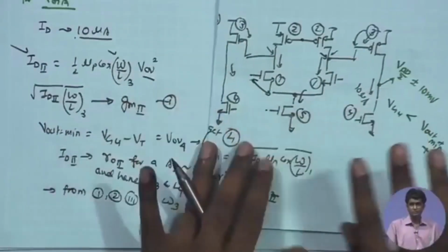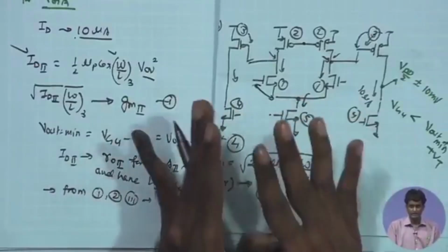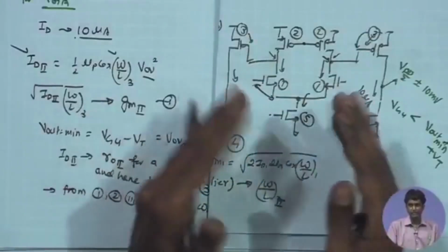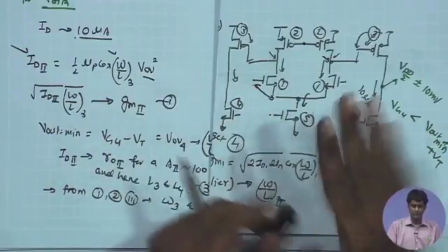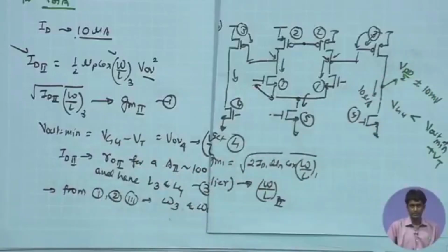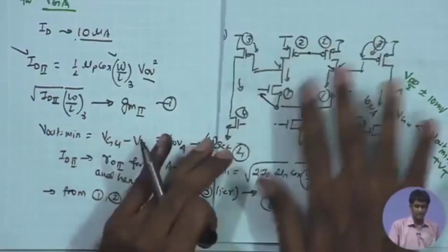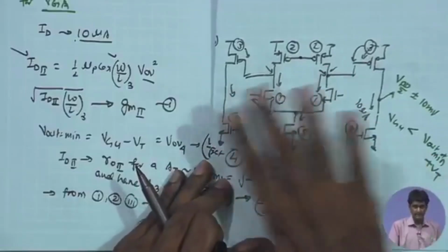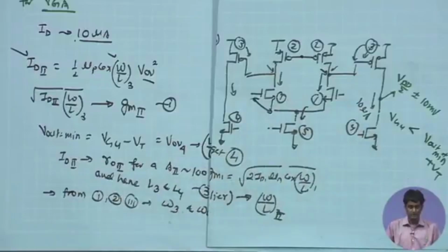So, we should just be careful about which constraint or parameter is critical and which is not, and based on that we can determine how to size, while getting advantage in terms of saving some bias current without messing up any other specifications. So, I have just presented some logical steps to facilitate sizing of the front end amplifier and the second stage variable gain amplifier.